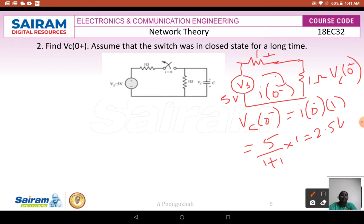So Vc of 0 minus is 2.5 volts after the switch was in the closed state for a long time. Now we are going to open the switch. When the switch is opened, it is Vc of 0 plus. We know that the voltage across the capacitance cannot change instantaneously. So we write that Vc of 0 plus is equivalent to Vc of 0 minus, which is 2.5 volts.